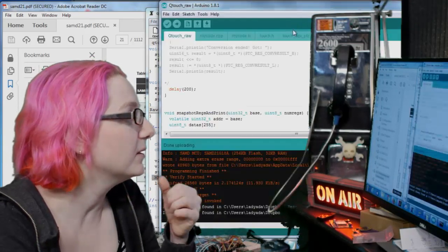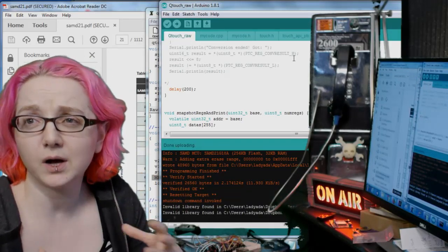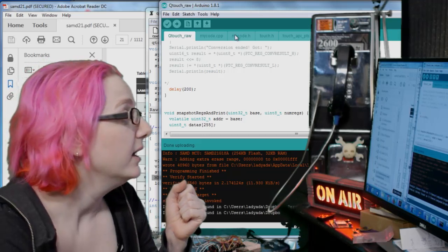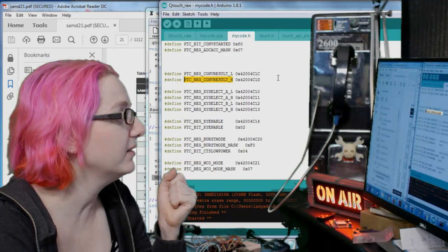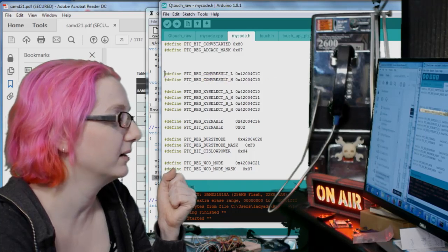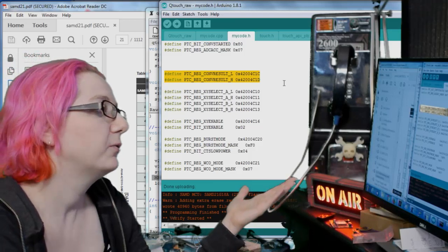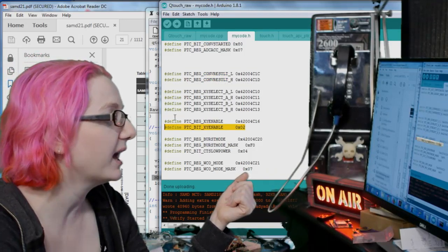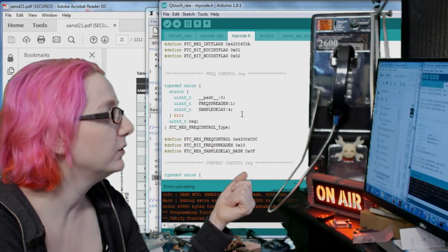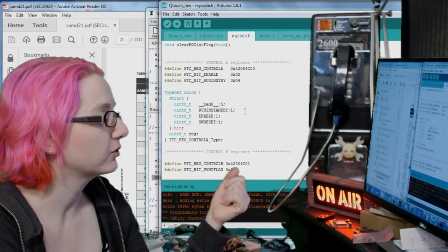They're pretty simple. With Atmel Studio for the SAMD processor, it's much more complicated and there are a lot of registers. So they did a pretty nice thing where instead of just saying this, which is like my shorthand, the register conversion result is in 42004C1C and the XY enable and this is the flag, what you do is you set up a structure. And I kind of cloned their structure setup.